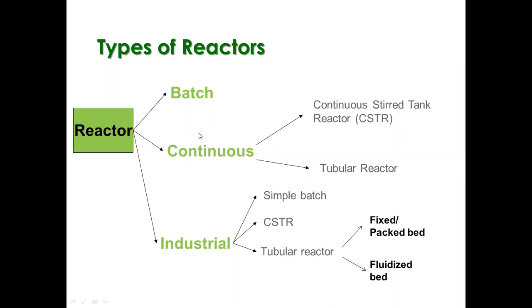That particular rate law will be applicable to the same kind of reaction even if it's facilitated in a different environment. What do I mean by that? Even if you're going to perform that particular reaction in a tubular reactor or in a CSTR, its rate law is its rate law, even if it was derived using a batch reactor. That is why what you have learned in midterm will still be your basis, and will be a big factor in end term, because you cannot design without the rate law.